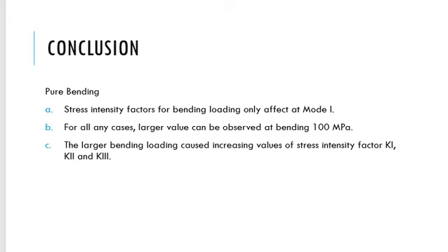For the conclusion, for pure bending, the stress intensity factor for bending loading only affects mode 1. For all cases, larger values can be observed at bending of 100 megapascal, and the larger bending loading causes increased values of the stress intensity factor for K1, K2, and K3.